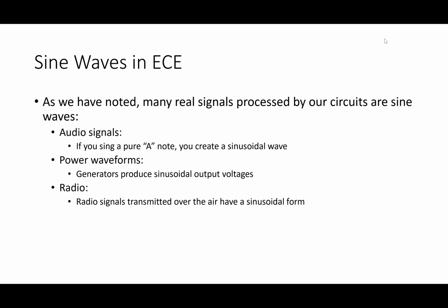Yeah, DC basically, as a function of time, stays constant, right? So if I watch a DC waveform on an oscilloscope, I see a constant value. AC, I'm seeing it change its value over time. And the good thing about any AC waveform is I can think of it as being a sum of sine waves, even if it's a square wave, right? A square wave is not a sine wave, but a square wave is a sum of sine waves. So for now, it suffices to say that that's probably enough for you guys to know.